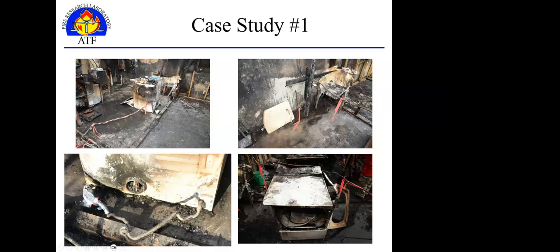So we recognized that there might be some potential for some wrongdoing here, some suspicious activity. It was also odd that if you look, this flexible gas connector is twisted. That's not a normal installation practice. So we recognized that this might be a potential data point. So we covered that connector end with a bag so we could submit that for tool marks to our lab and have them look for evidence of, was this disconnected intentionally?